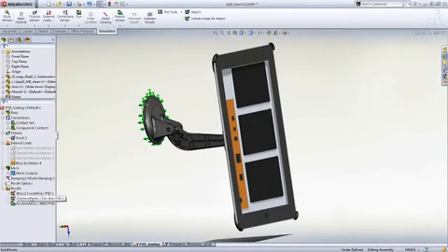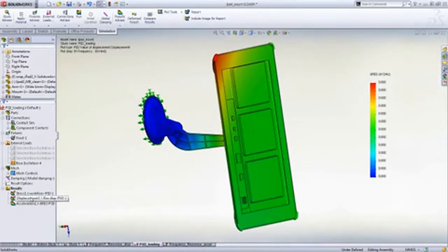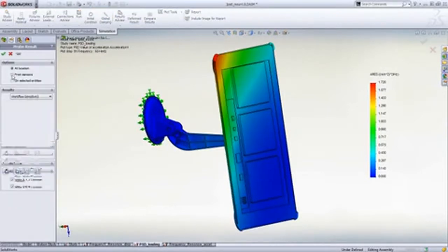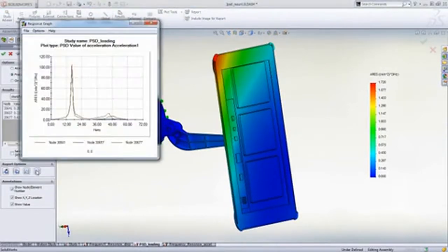By understanding the design natural mode of vibration, you can carry out preventive measures such as changes in material, in components, dampers, and so forth, so that your component's natural frequency does not match with the frequency of the loading environment. This results in a design that will not only perform as desired, but also have a longer service time.